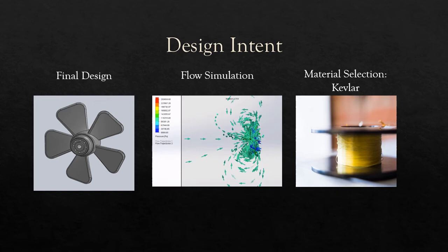In terms of material selection, the team wanted to use a lightweight and more resistant material than ABS that could be implemented in additive manufacturing. Kevlar has been the most promising due to its excellent strength-to-weight ratio. 3D printed Kevlar is 3 times stronger and 12 times more rigid than ABS. Kevlar also has some benefits when it comes to 3D printing, including cheap replacements for manufactured parts and smooth print due to its long and regular molecular structure.